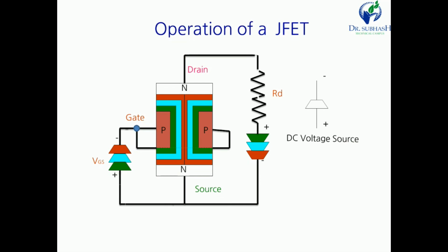First of all, you have to remember this type of characteristic, this idea, for the designing of the JFET. Now in this slide we have seen, if we increase the voltage, first this green voltage, then blue, then red voltage, then what happens? If we increase the voltage, then the channel width will decrease and depletion region increase, so the current becomes very small. At the time the two depletion regions touch each other, it becomes pinch off, and current becomes constant. This is very important for the JFET.